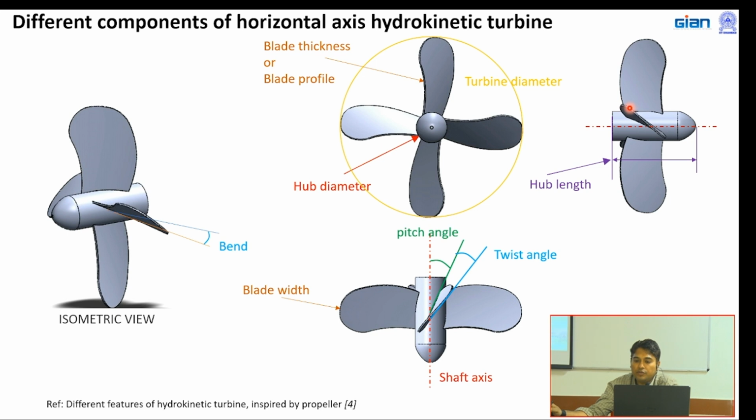Now if you see this part, this is the central axis, or axis of rotation. This axis of rotation will definitely pass through the blade somewhere here. If I consider this part of the blade, it is touching this axis, and this part of the blade is also touching the axis initially. Now I have given a twist like this. Initially it was like this, now I am giving a twist like this. After giving that twist, this type of alignment of the blade will be present here.